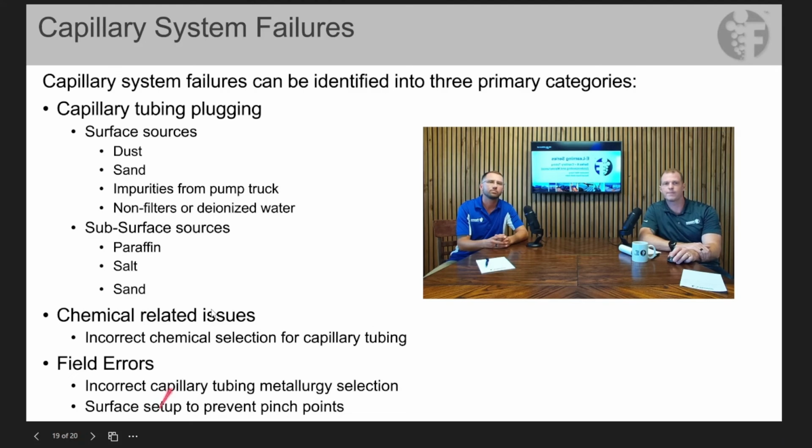And so, why would stuff plug up? One, it's pretty small. But sand and dust are a big one. Filters not catching what they're supposed to be catching. 25 micron is definitely a good filter to keep in mind.